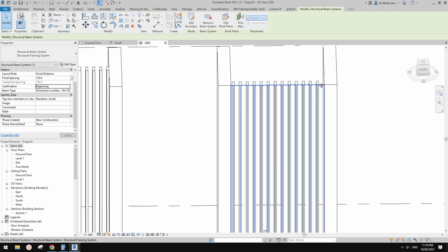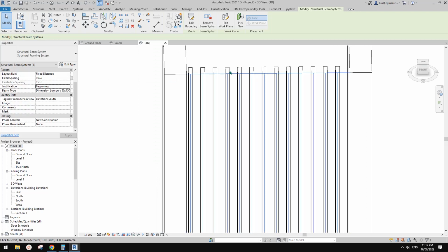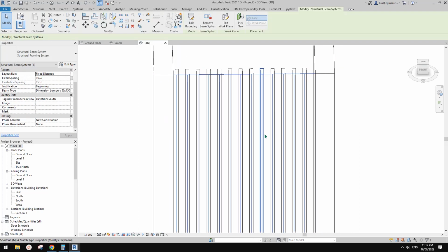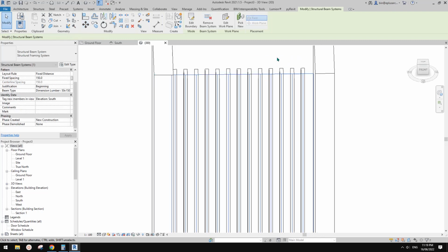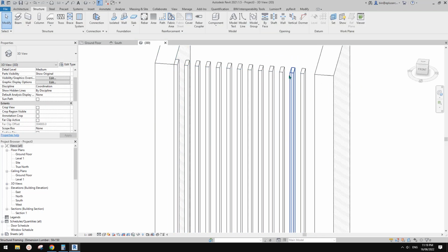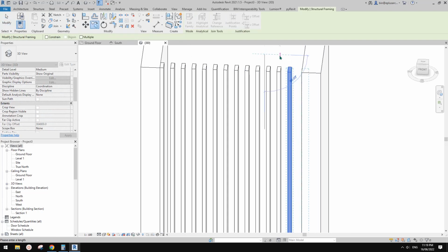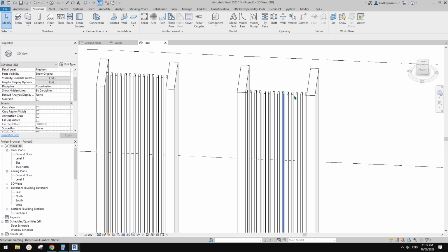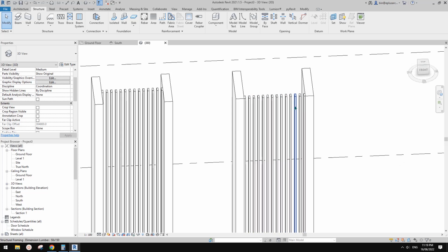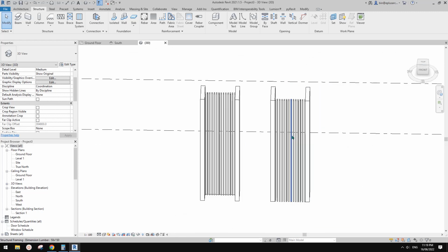Okay, so it seems it, yep. So it's from here to here, 150, which means if we move the whole thing, you can simply select this beam system, move it by 25, I think 25, and then this will match the size. Then simply select this one, select this individual beam, 150, and then that's it. Okay, so you won't be able to create a perfect one in just a single step. You need to adjust a little bit. Okay, so this is the second method, beam system.